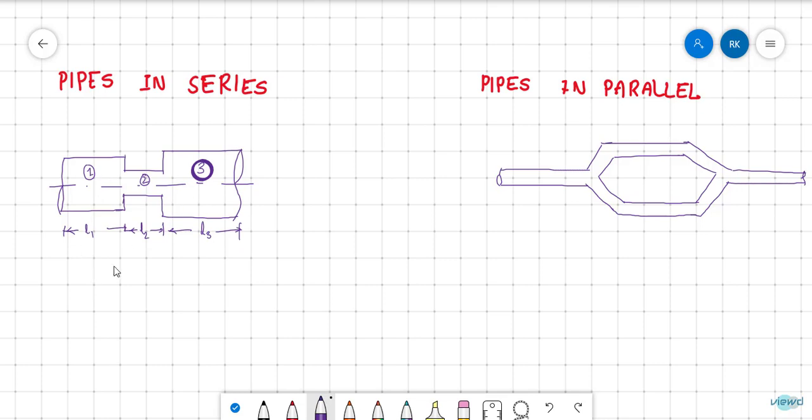So what about the discharge? Discharge will be constant, since the only thing changing is the cross-section area of the pipe, and discharge will be constant when there is only one flow and no branched flows. The fluid is not distributing to other pipes, it is only flowing in that pipe, but of different cross sections. So discharge will be constant, that is, area into velocity is constant.